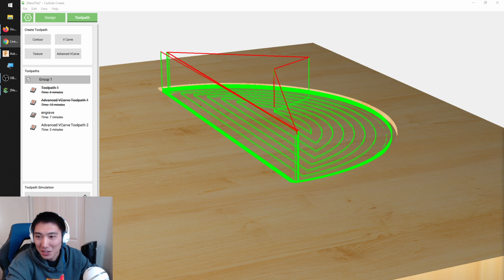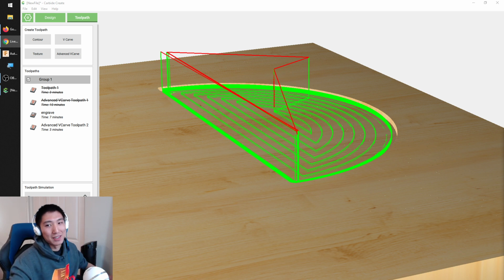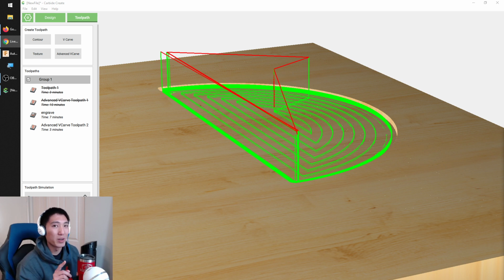I love you too. Are quarter-inch end mills useful with the Nomad when cutting aluminum? Yes and no. So quarter-inch end mills generally require a lot more torque to use, and for the Nomad that's not great. But if you use a single flute end mill and you use an adaptive toolpath, or you're just doing facing, that quarter-inch diameter cutter has a much faster edge velocity, and that'll leave a much nicer surface finish, and it'll be quieter. So our 278 actually works really well. It'd be nicer if we got it a little shorter so it didn't stick out of the collet so much, but you can use a quarter-inch end mill if you're smart about it.